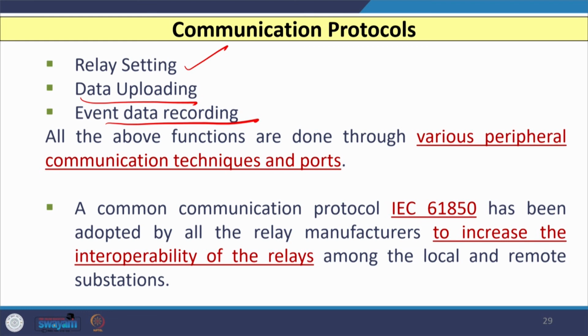So, in this lecture we started our discussion with the input output flow in the PMU. Then we discussed the different errors possible in PMU, and we discussed three important errors. One is the total vector error, second is the frequency error, and another is the rate of change of frequency error. And then we also discussed how we can calculate those errors using equations, and at last we discussed the implementation statistics of PMUs in our country, and based on URTDSM they have suggested certain recommendations that we also discussed.